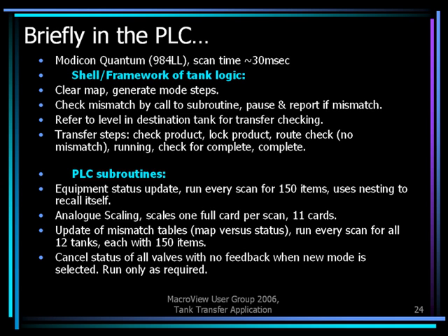At this stage it's usually a question of cost, that the client decided that there's a valve there. They need to know the situation of it, display it, but it's not automated as yet. There's potential to be automated or have feedback in the future, and that's part of why we're taking this approach, because it's so easy to change the style of the valve down the track and not have to rework the system too much. But Brad, also, the only way we could think of doing it is we can log when they click on closed that they have clicked closed.